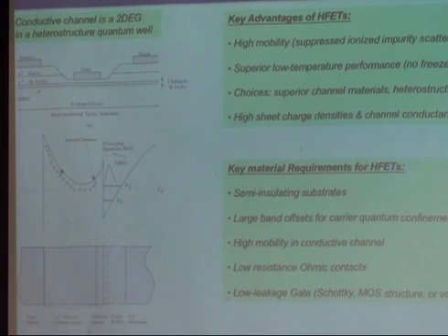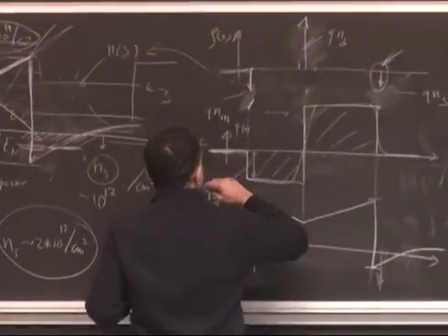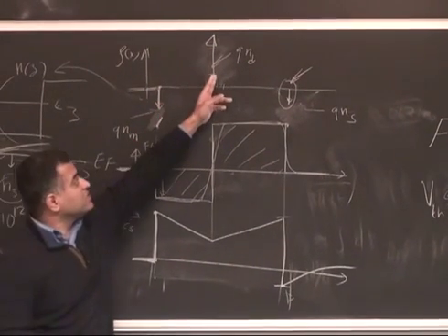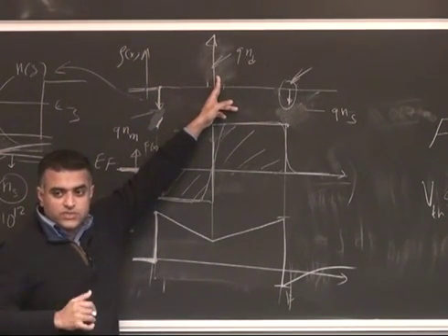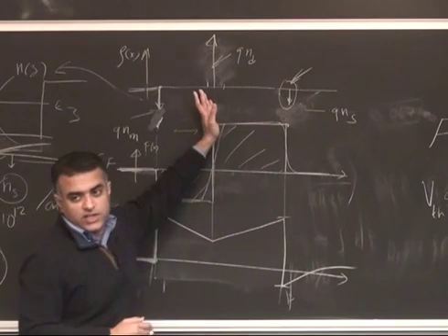Now we are going to apply gate voltage and try to remove the electron gas. I think it's very clear that you want to apply negative voltage to remove that electron gas, right? And the question is how much? 0.2 volts, 0.5 volts, what determines that voltage? You can see what will happen in the charge diagram when you apply the voltage. What happens here when I apply negative voltage? Does this change? No. Ionized donors, they remain ionized. This doesn't seem to change, right? So all that will happen is this is mobile, that's mobile. The ratio of these will change.